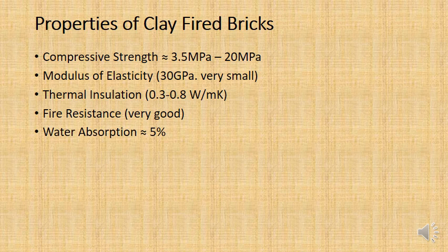And that's because of pores inside the clay-fired brick. So remember, clay normally has a very high porosity and absorption capacity of maybe 20-30%. After we fire it, it brings the water absorption down. And remember, porosity is a bad thing, because if it's high porosity, then the material will break down and it will degrade. There will be no durability with the material.